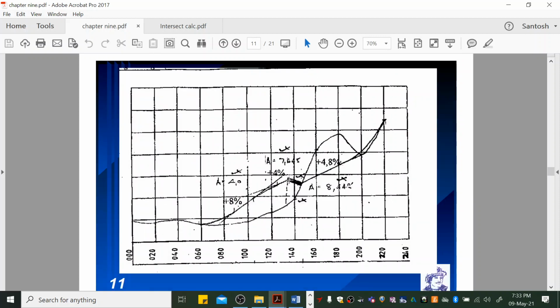So we've gone and tied in from that point. Okay, now you don't tie in from the top point, you tie in from the middle or the bottom point, simply because we're designing to top of earthworks, not to top of finished road level for intersections. So we draw a line 4%, 25 meters away, coming out. And at that point, we can draw another line coming down so that that line meets the ground level.